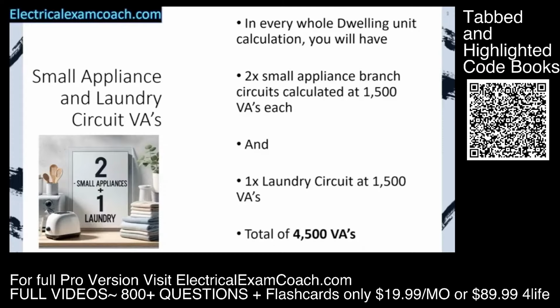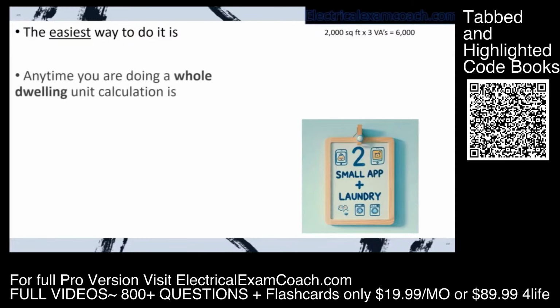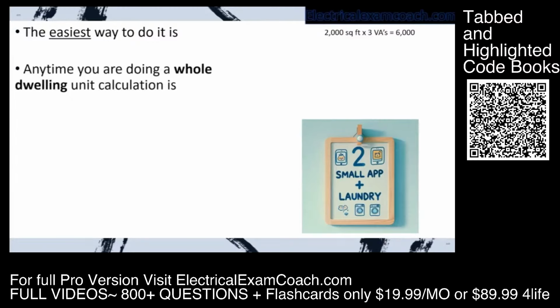Now, this is something that we're only going to do and attach it to the general lighting load and receptacles before demand factors. We're only going to do it when we're doing a whole house load calc. We are not going to add it on to something like an individual dryer or an individual range. Those are calculated individually. This is only when we're doing a whole home load calc. And once we start doing them, I will make sure to reiterate to you so you understand when and how to apply this.